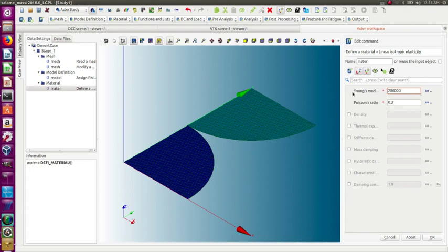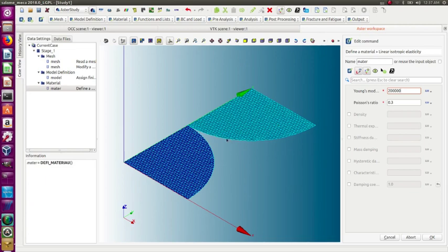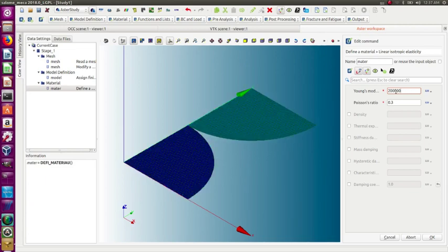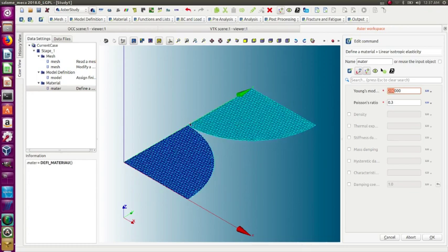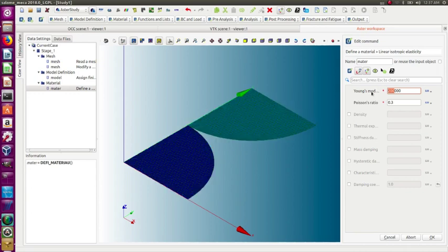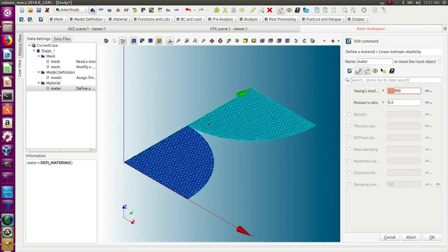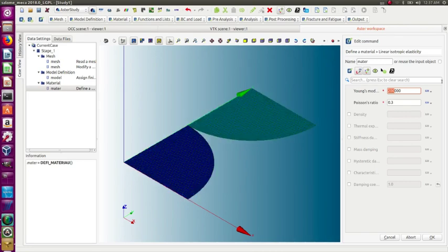So why am I choosing a Young's modulus which is lower than the actual real value of steel if I was to use steel? It's because I want to make this model a bit more flexible, so you see what happened in the contact area. If I increase too much the Young's modulus, as it would be in reality, this would be simply too stiff here, and we wouldn't get a very nice distribution of the pressure. So that's why I'm using this value. But always be careful about the unit and ask yourself, well, is this unit I'm using the right one?